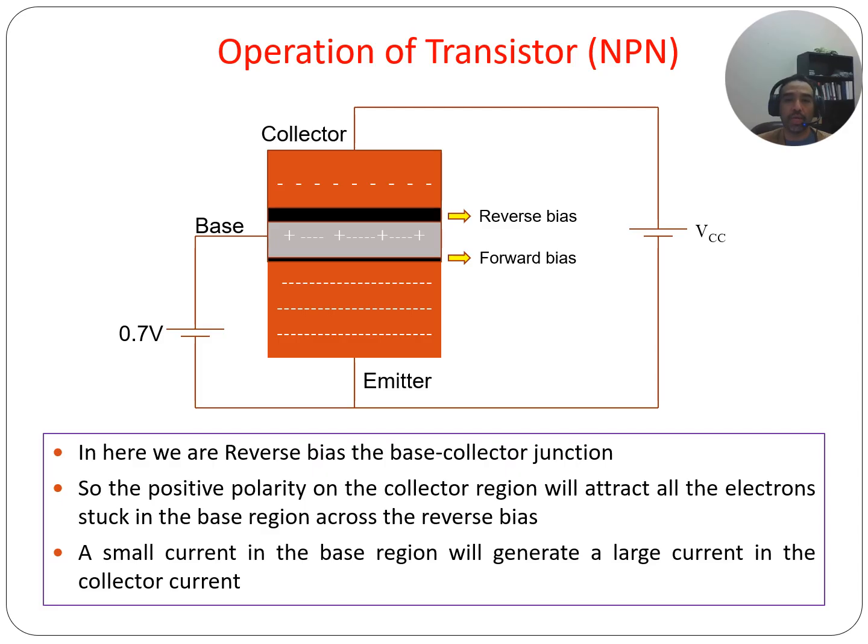So we have current amplification. You have a small current that flows through the base because of the applied voltage on the base, and that leads to a much larger current flow through the collector. This is due to the way the transistor is designed and how the reverse bias affects the flow of electrons. So a small current signal in the base gives a larger proportional current flow from the collector to emitter, right?